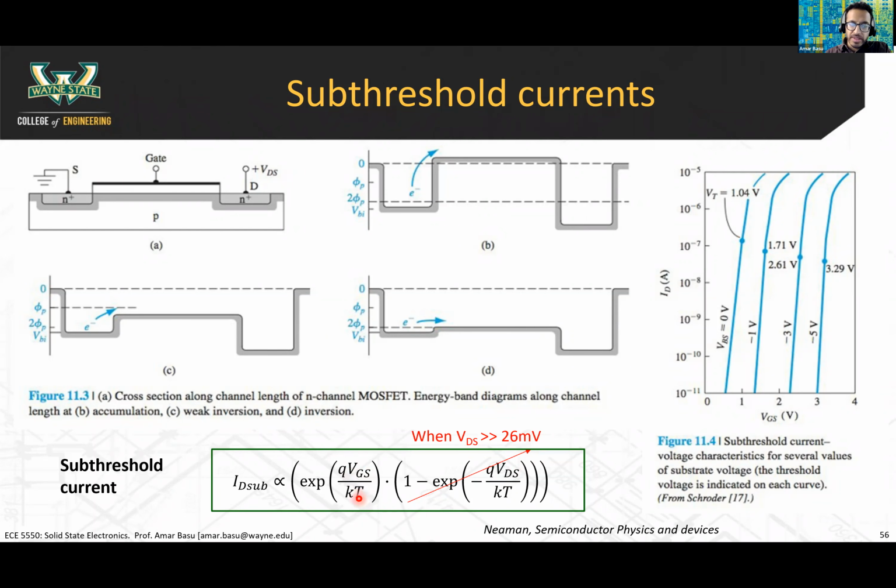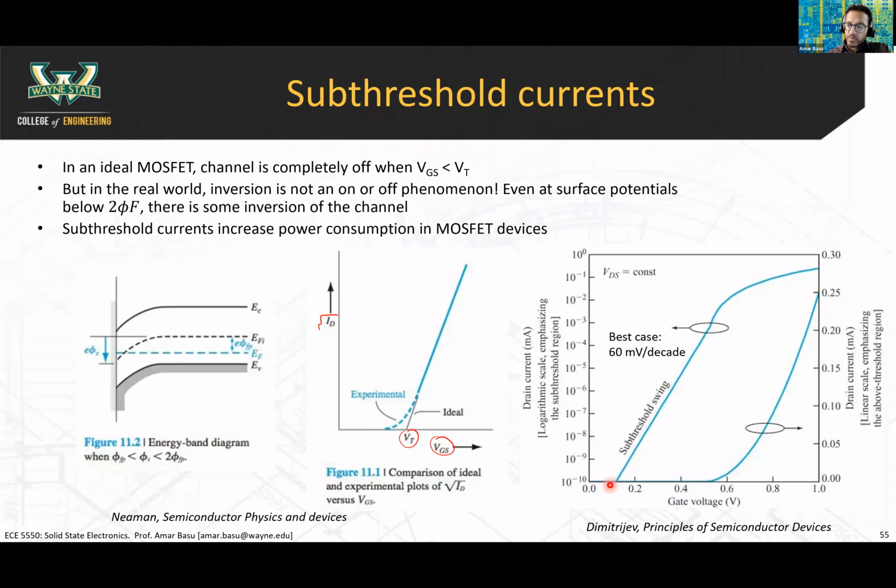Notice this is an exponential of VGS, and KT over Q is 26 millivolts. Because of this fundamental relation, and because this is an exponential of E, you end up getting this classic curve that you see here, which is called the subthreshold swing curve.